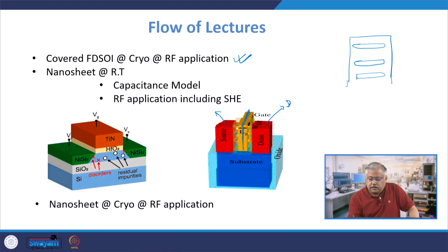And this is the gate here. So this is channel number 1, this is channel number 2, let us say channel number 3, and this is a metal gate, and then there is an oxide layer which is surrounding the channel in this manner. It's actually a FET device, and it's also a MOS structure. Just the fact that now, rather than having a single channel, you have multiple channels available to you, and that improves the drain current to a larger extent.